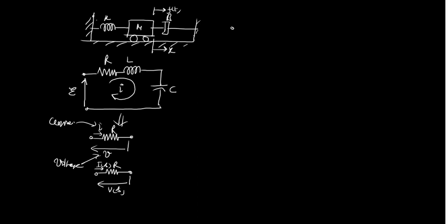Clear? Then we have also discussed that if we have an inductor, with the current flowing through it iT, the inductor L, and the voltage across it V, it is represented in the Laplace transform domain like this: SL and Li0.